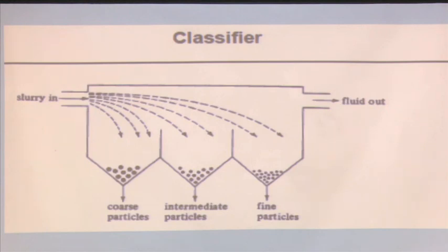So, how do I maintain this uniform depth, because I have to collect that. That is why you get into that basic design, and the fundamental thing I need to know is the settling velocity of the particles. Okay, that is how we can use it.